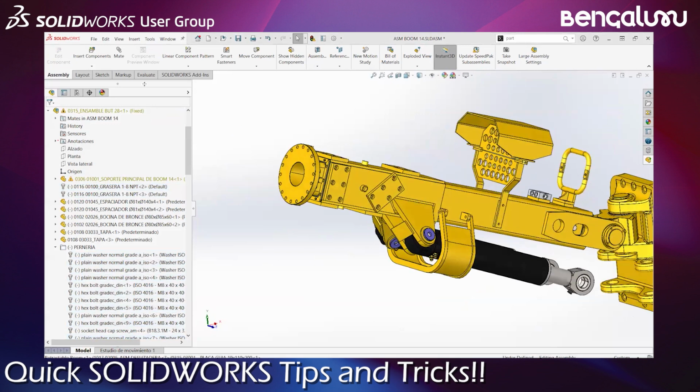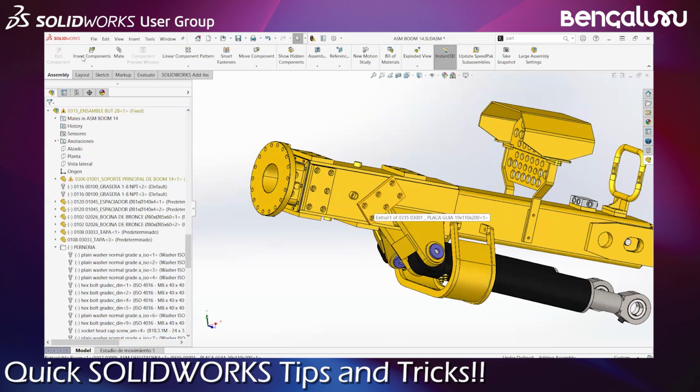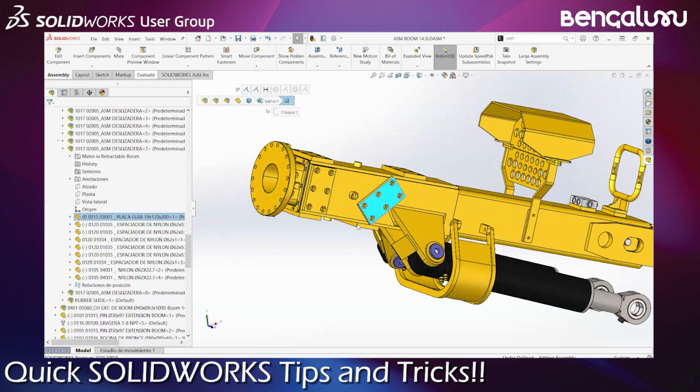So the next thing is when I want to insert a new component, for example, I want to insert another instance of the same thing. So I need not go to insert components every time. All I do is I select this component and hold control and then drag this. And I don't leave control first. I first leave the mouse click and then leave control. So now you have another instance of the same part.